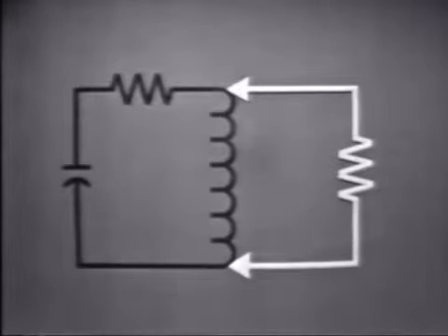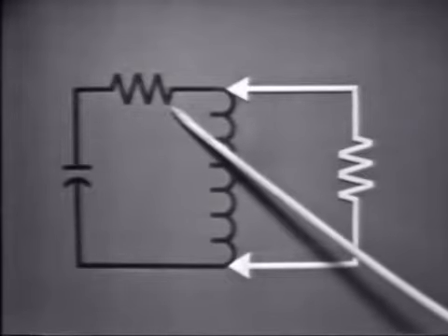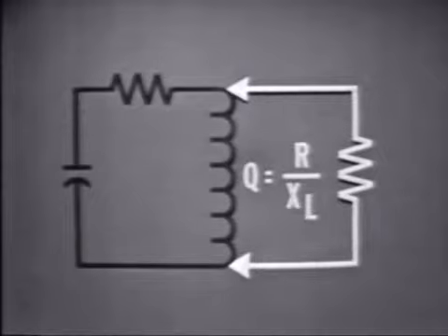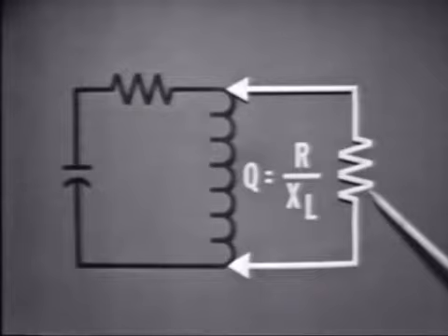One other factor should be considered, and that is loading the oscillator circuit. We can see this effect clearly by looking again at our basic circuit. We've already pointed out that the feedback overcomes the loss caused by the internal resistance of the circuit, which is small when a high Q tank is used. However, there is another quality factor that concerns external circuit resistance, and in this case, the resistance should be high.